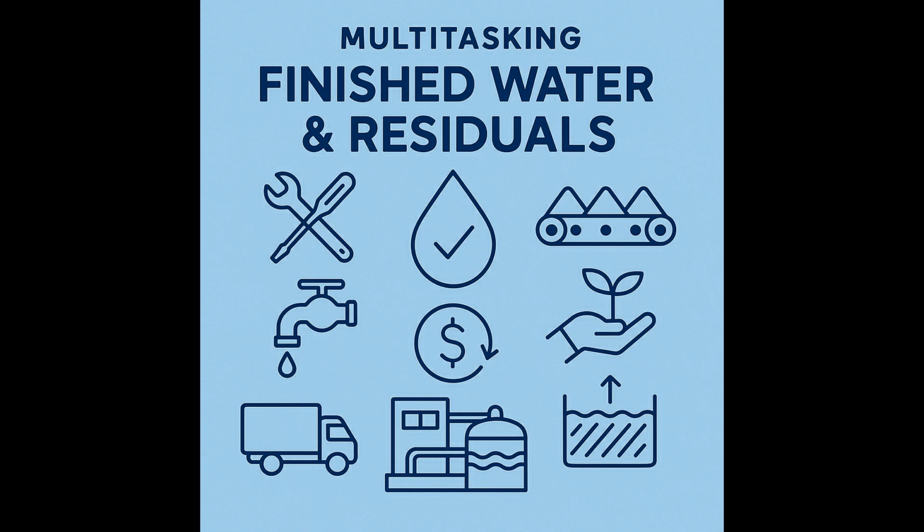Okay, screens take out the big stuff, then the water goes to rapid mix and coagulation. That's where they add chemicals, right? Yeah, chemicals get dispersed really quickly to destabilize the tiny particles floating in the water. At this stage, you're not generating a big continuous waste stream. It's more like the precursors to the sludge are forming. Mostly the waste here is just empty chemical containers.